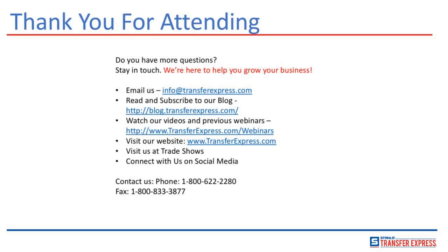If you have used EZView before, though, I encourage you now to go there, jump on, and mess with it a little bit. Play with the vectorizer. If you don't have a file, find just a simple bitmap on your computer somewhere. Find maybe a local high school's mascot or something like that. Grab that and put that through the vectorizer. Remember to start with something simple. If you have something super complicated, it's going to overwhelm the designer and it's not going to work.